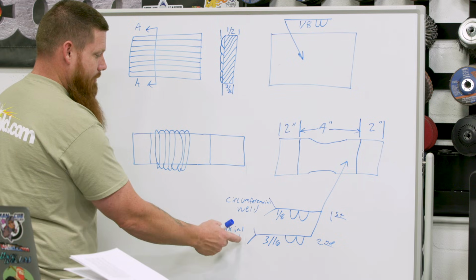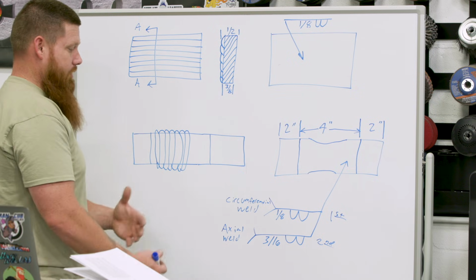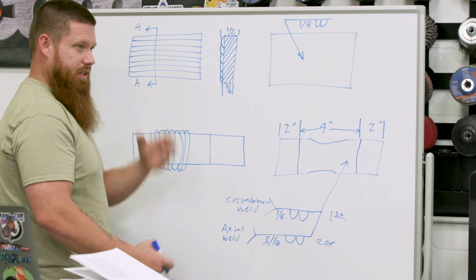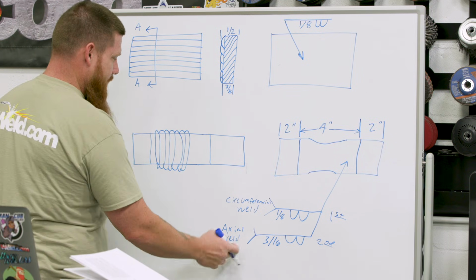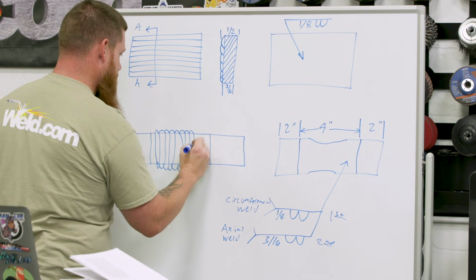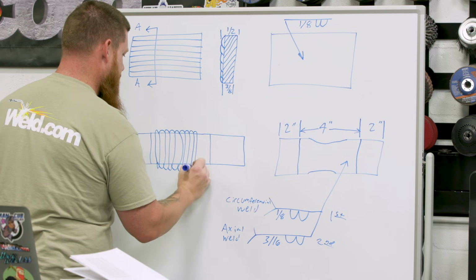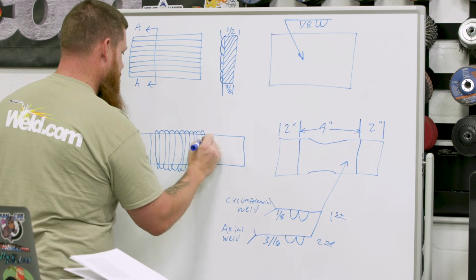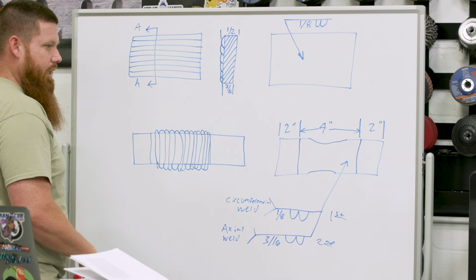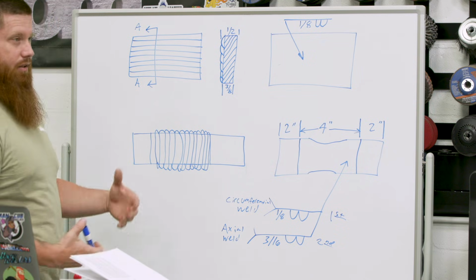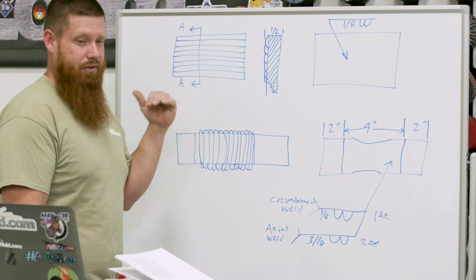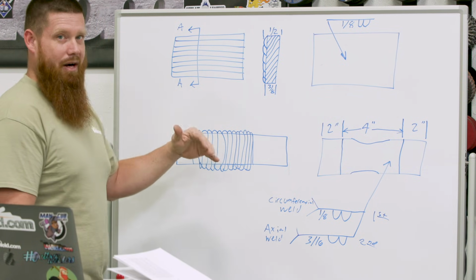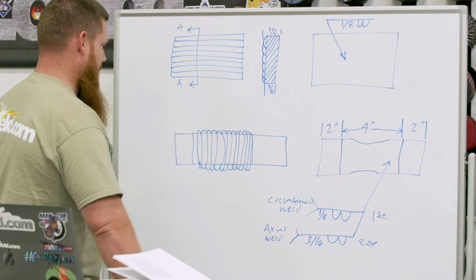They could even tell you what type of welding rod to use in here if you're doing hard surfacing, or you have a specific composition of material. That information would be in your tail as well to tell you what type of electrode you should be using, or process. I have some previous students that do this. They work at a recycling facility, and the parts that crush up the cars are constantly getting resurfaced just because it's cheaper to repair it than it is to replace that entire shaft.